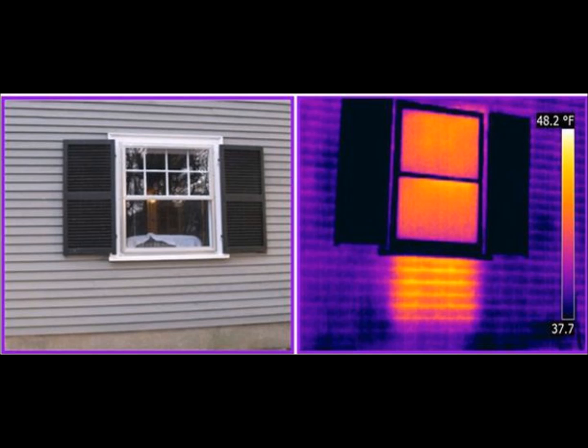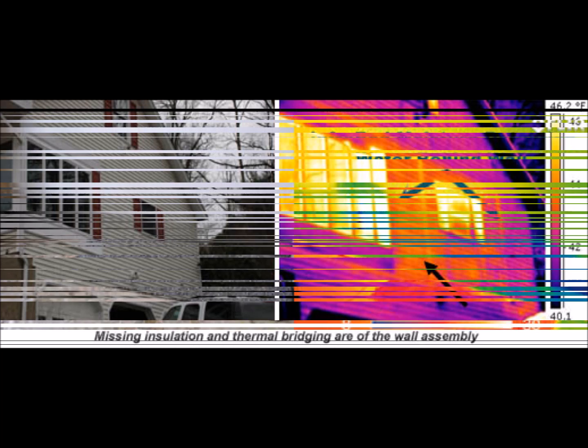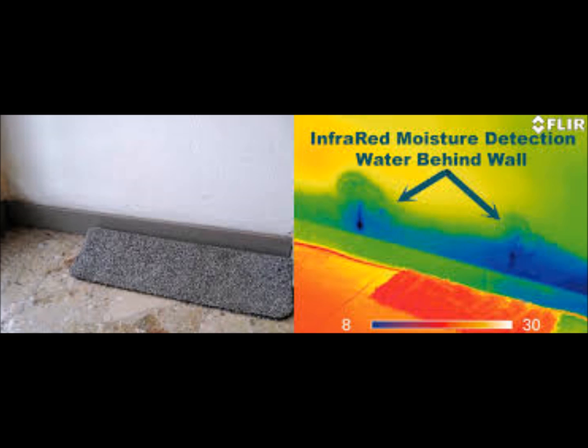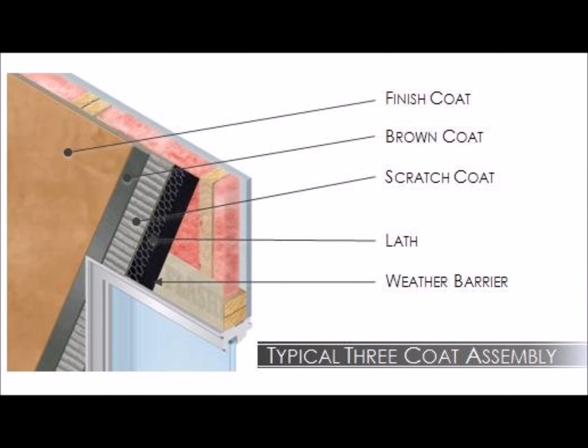If you have siding such as metal, wood, or vinyl, it does not provide an additional air barrier. If you have two-coat stucco, usually applied over a brick wall, it allows for a greater hydric buffer, but unless there's sufficient drying time allowed, moisture is retained in the brick. If you have three-coat stucco, this does add a waterproof layer of sheathing paper. However, this system has a lower hydric buffer capacity, but it makes up for it in the added waterproof layer.